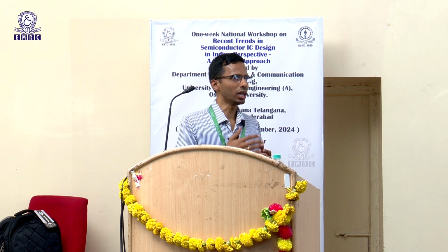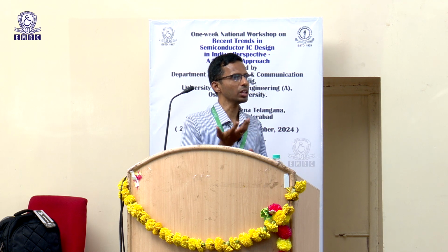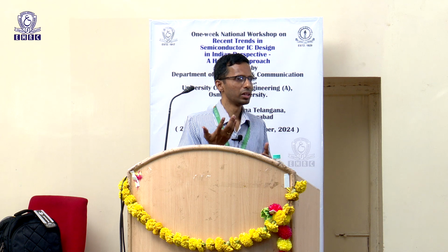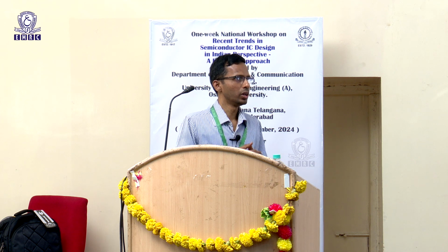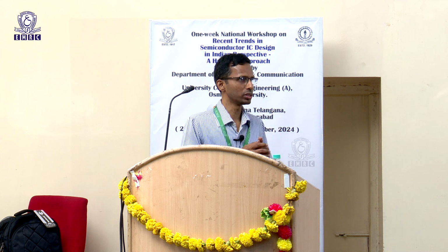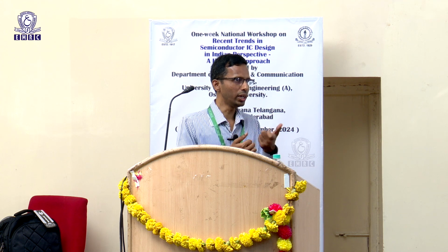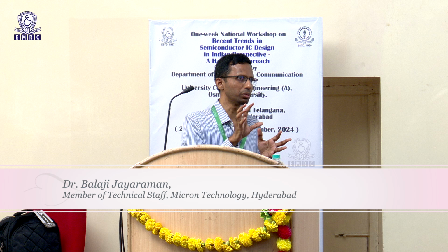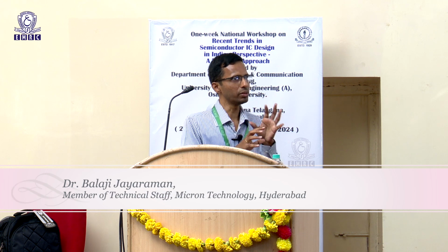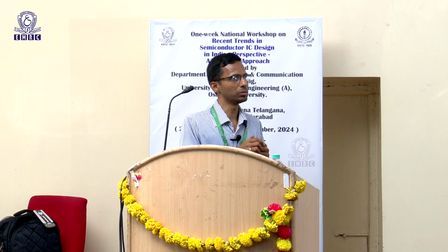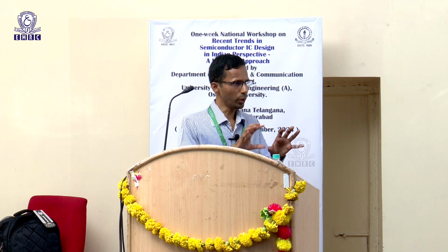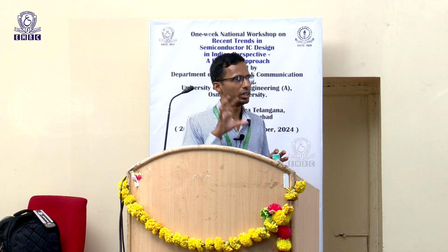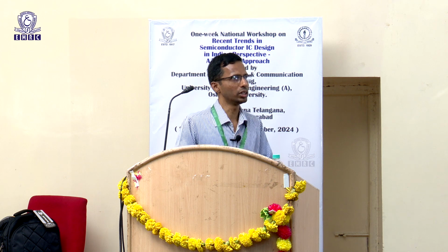And then of late, you started using write assist circuitry, wherein you use negative bit line voltages. To realize this negative bit line, you again need negative regulators or negative charge pumps. So that again is an analog block. The sense amp to some extent is a mixed block, but apart from the sense amp, you have voltage regulators and charge pumps that go in there as well. But if you were to compare SRAM versus DRAM, DRAM has much more analog components in it, I would say, as compared to SRAM.